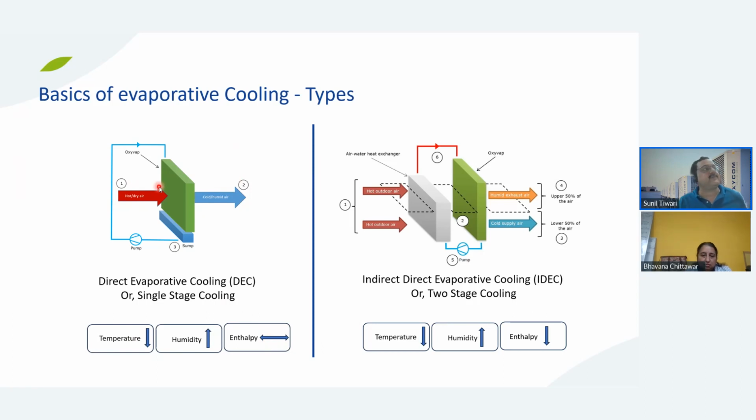Sometimes I come across audiences who say, okay, I will use evaporative cooling, take this air and put it into my air handling unit. So I am putting low temperature air over the coil and I will have some energy savings. That's a misnomer, because you have removed the sensible heat, but you added the equal amount of heat in the form of latent energy. So actually, it is not going to do any saving on the tonnage that is required through the cooling coil or chilled water coil. So that's where it is an adiabatic process where the heat remains constant.